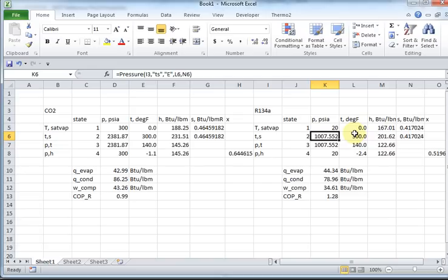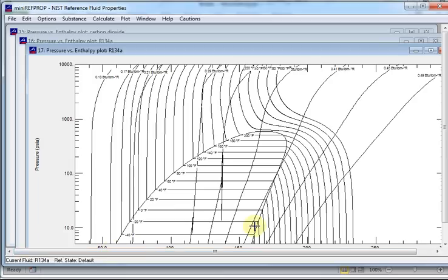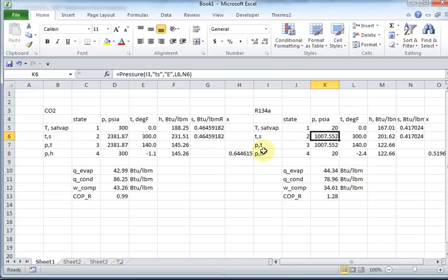Oops. Escape. I needed to stay with temperature S. So let me do that. Let me go back to my plot. Okay, 0. I'm going to compress it isentropically until it comes out right in this vicinity, about 180. That's my guess. Okay. So let's go back to Excel, and temperature of 180. Did that work? Let's get rid of these. Boom, boom, boom, boom. It's still pretty high. Maybe I don't need to go out that high. 160. Here, that looks more reasonable.